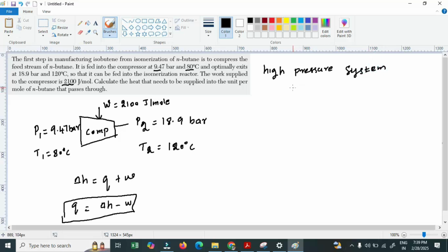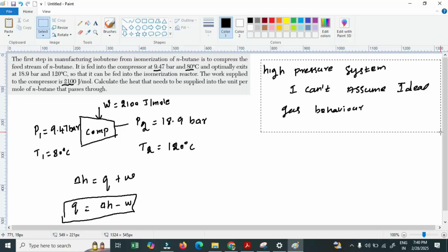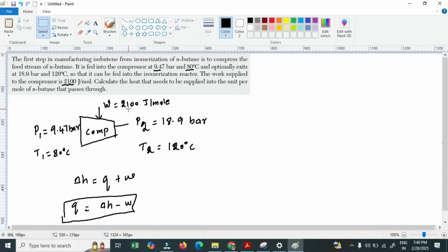Now, since it is a single component system, and let me assume it is a single phase system also, as per the Gibbs phase rule, we need two intensive properties to define the system. Let me assume enthalpy is a function of volume and temperature. You can assume enthalpy is a function of pressure and temperature, or pressure and volume. Whichever way you want, but let me choose the mathematically simplest way, that it is a function of V and T.